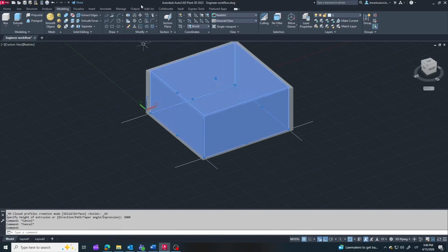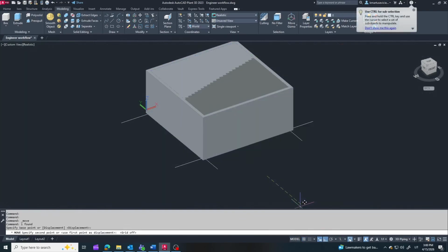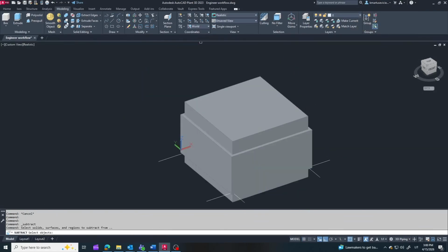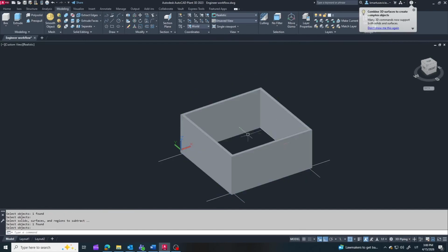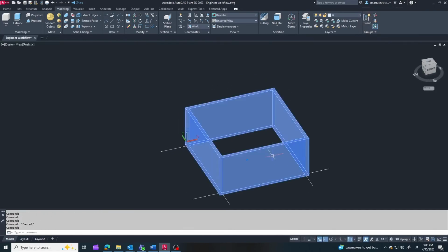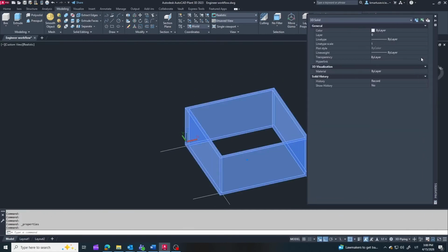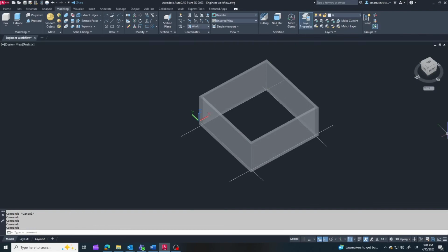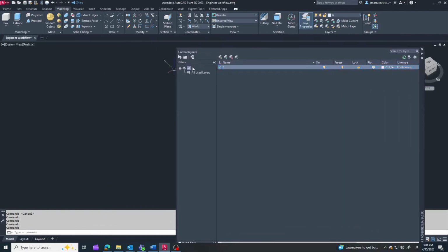In real projects, we almost never design equipment in the air. Pumps and tanks are always placed relative to something: existing buildings, structures, or defined coordinates. If it's a new area, we still need reference points to work with. That's why I always start with axes and basic walls. It gives structure to the model and makes every next step more logical.